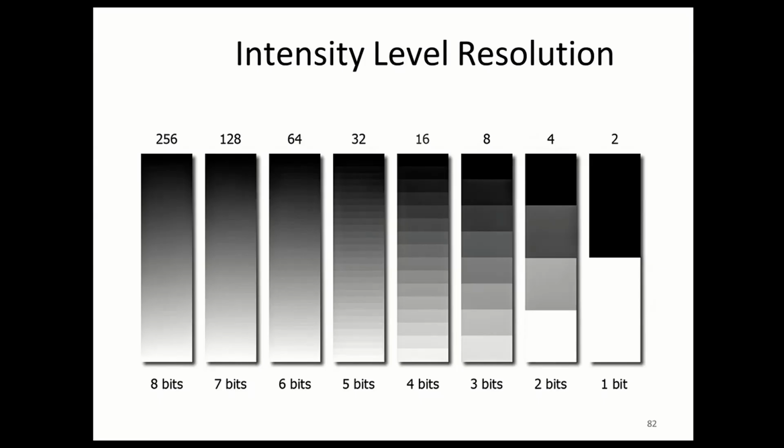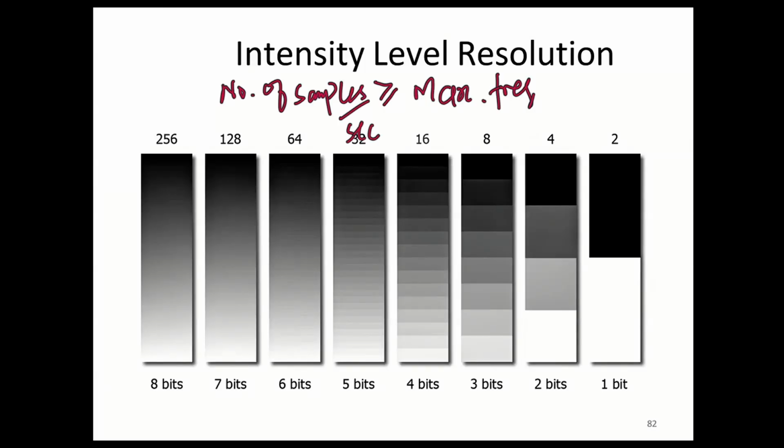What is the Nyquist theorem? In order to obtain the number of samples, the minimum. Yes. The maximum depends on your storage, and the minimum will be decided by the Nyquist theorem. It depends on the maximum frequency in your signal for the image. So for samples, the frequency is greater than or equal to that maximum frequency in your signal for the image. Yes. But this we will cover in the Fourier transform. That's why I did not discuss it here.